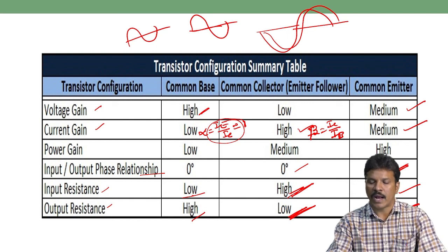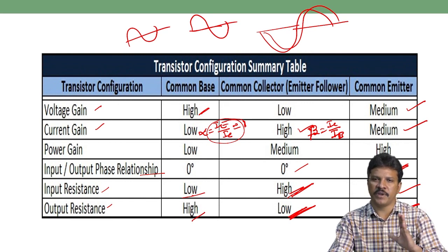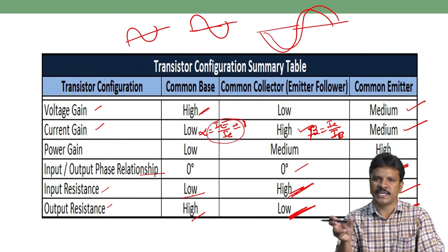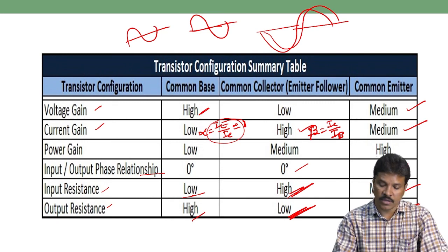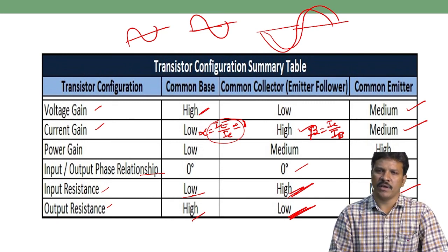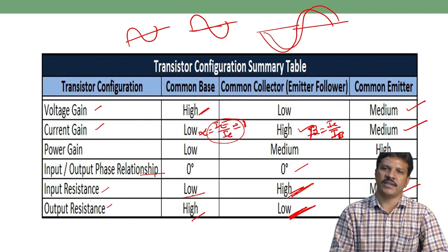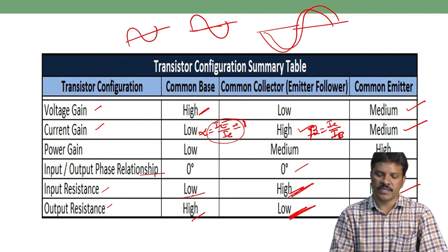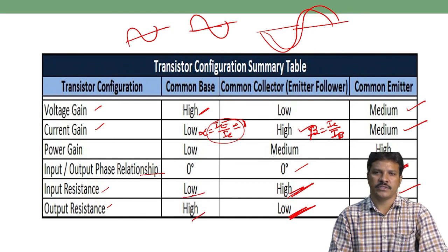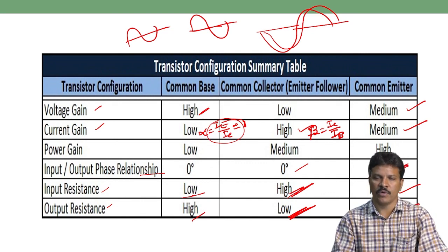And common emitter is the intermediate stage. Always prefer it as an intermediate stage, like in the amplifier, to improve the gain. To improve the gain, we can use multi-stage common emitter amplifiers in amplifier circuits. So in this way, we can prefer each configuration in each different situation. The purpose of these configurations changes with the application. So this is about the transistor configurations.